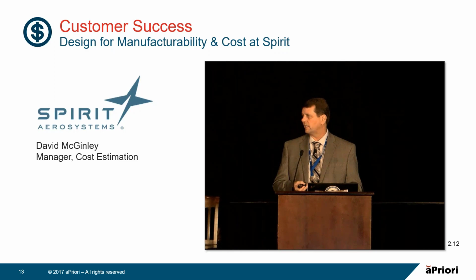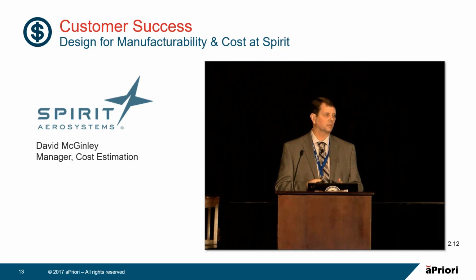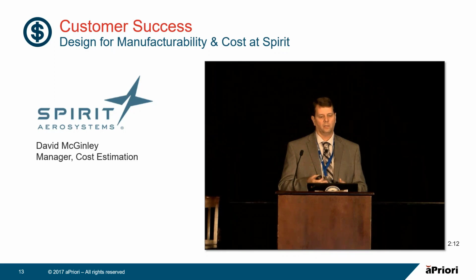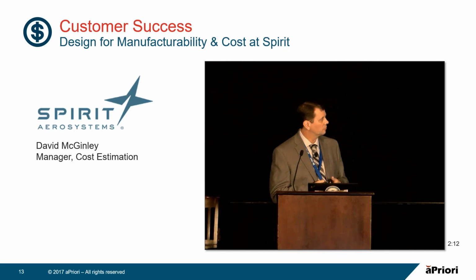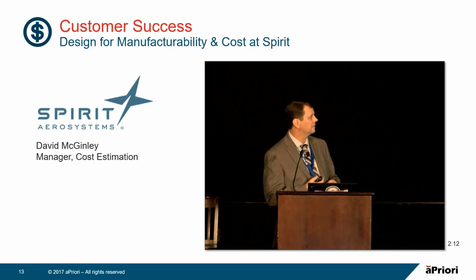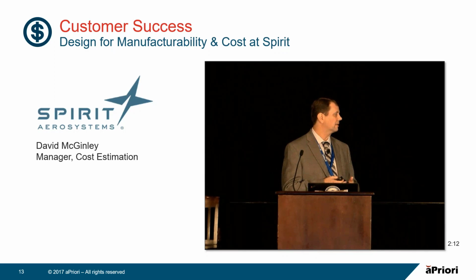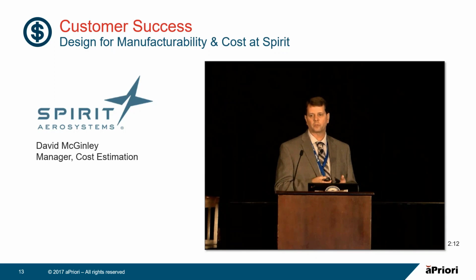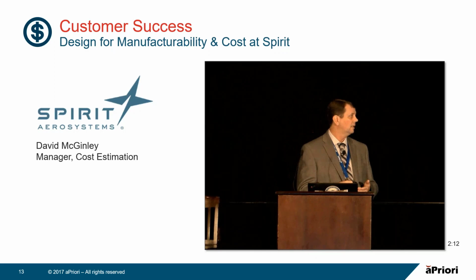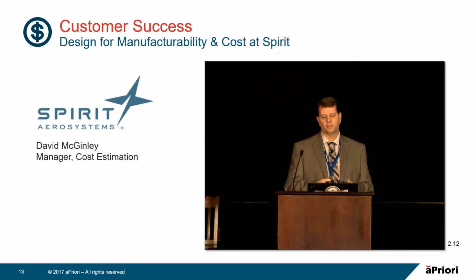So as we went through that, engaged in dialogue about requirements versus what looks nice, they came back with a revised model where they removed the radiuses and changed the fillet so it would accommodate a better cutter path, changed the contouring to some planar surfaces, and I think actually those pads are even gone today. There was some further discussion about were they even necessary at all. And with all those changes, the opportunity was to reduce that cost by about 11% for this part for a very minimal, almost negligible weight change.